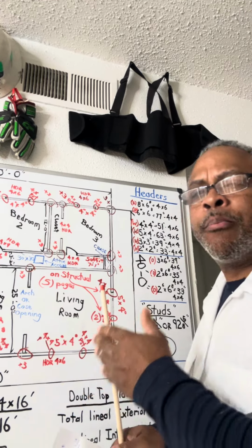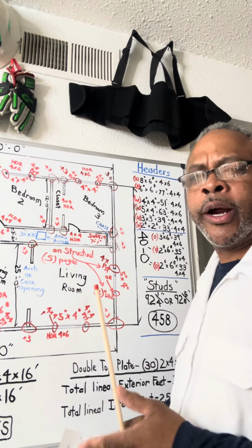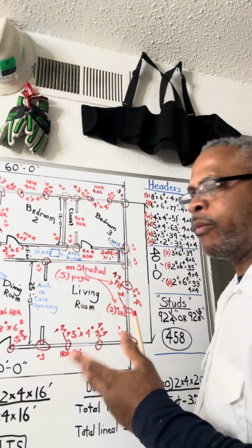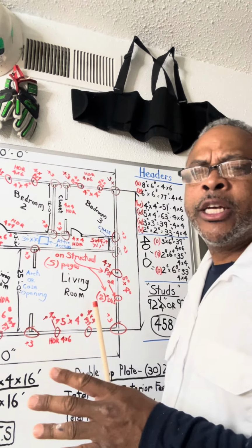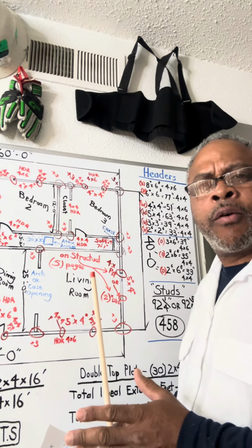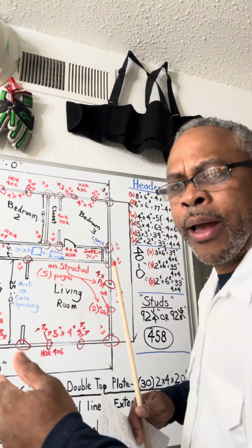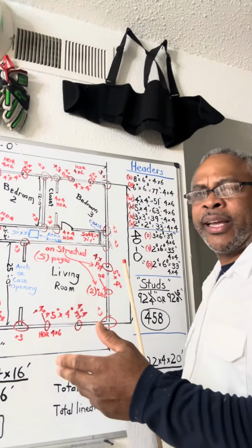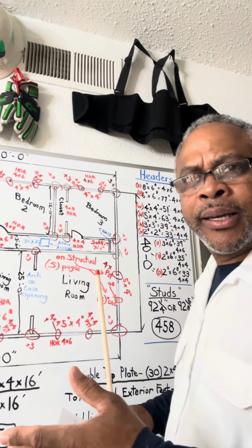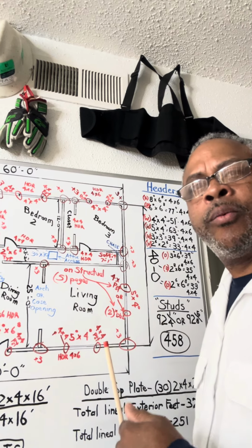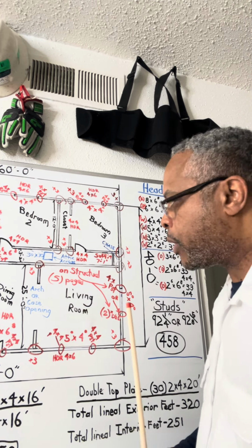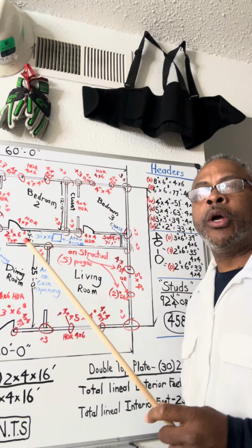And then if you have breaks and it's not over a stud, they're going to be requiring you to put a stud up underneath a break. They're going to require straps in certain locations so a wall won't separate itself. You'll put an ST strap, might be an ST16, could be an MST, an LST, depending on what the engineer calls out for your structural. The structural blueprints are always going to give you what you need.